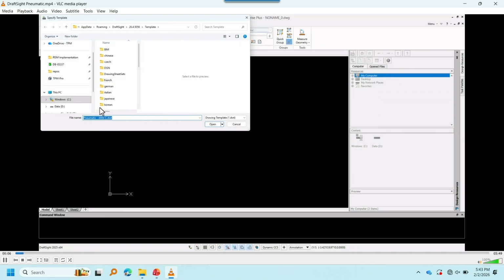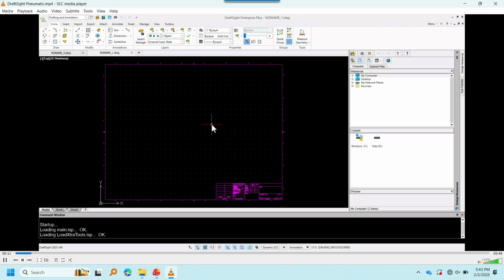modification. Now for pneumatic or hydraulic schematics, I want to take advantage of the palette, and also templates. So let me pause for a second. I have this template set up. You can have a grid in DraftSight set up for a certain X and Y direction spacing, and you can either turn it on or off. When I was doing a lot of my mechanical design work, I had it off. It just got in my way. You'd have the thing snap to that grid. For a diagram, it's very helpful because it helps you place those symbols.